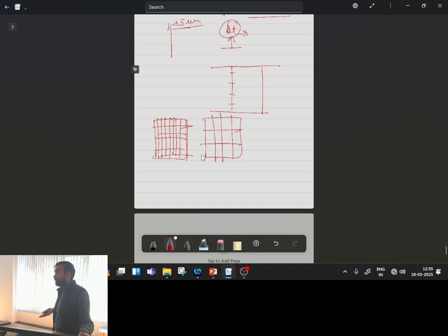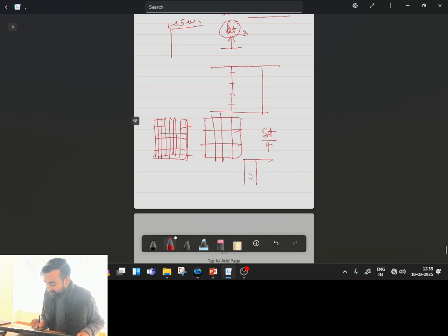So ultimately the selection of the time period at which we capture the images and the selection of the grid size are two important aspects which we have to simultaneously optimize to get better results. We will vary these during our measurement, and the point where the variation in the velocity field vanishes upon further decreasing delta t and delta x, we will consider as the ideal selection.